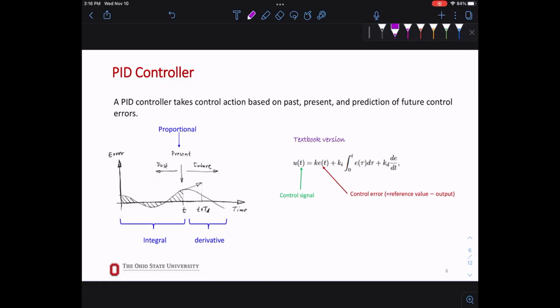Now, the proportional part: okay, I have an error of 10 centimeters. I was going to go to 10, I went to 1. Every time, instead of going to 20, I'm going to 2. So there's a scale in my error. If you get your signal and multiply by 10, you'll get where you're going to go. That's your proportional. So P controller, usually you just see as gain.